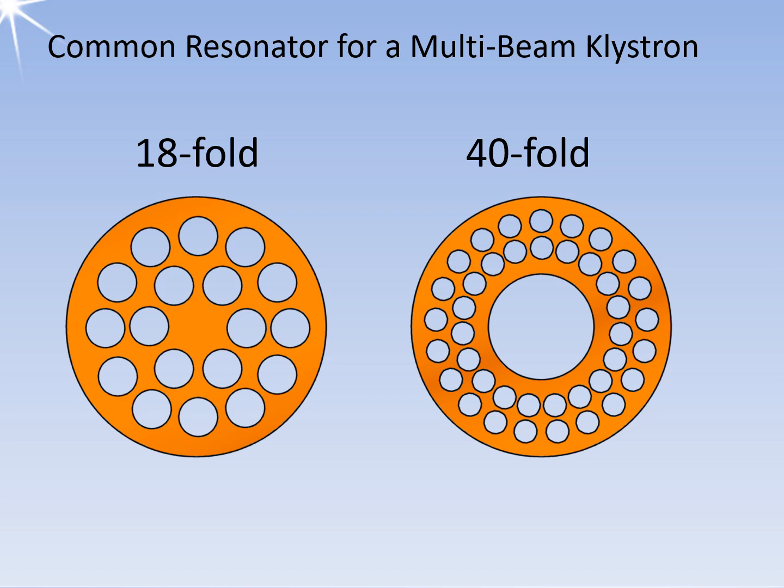These types of multi-beam klystrons, with a pulse power of up to over 100 megawatts, are used primarily in research for particle accelerators. Frequencies from the UHF band to the L band are required there. This makes the klystrons 2 to 3 meters long. The dimensions of the resonators also set an upper frequency limit. Klystrons with classic cavity resonators can be manufactured for frequencies up to 35 GHz.